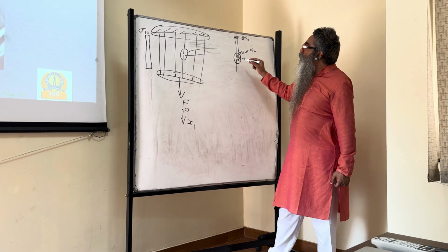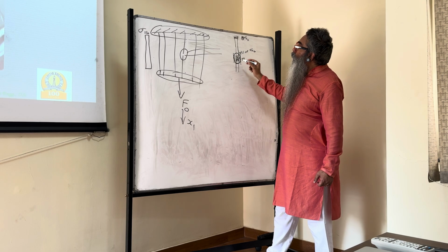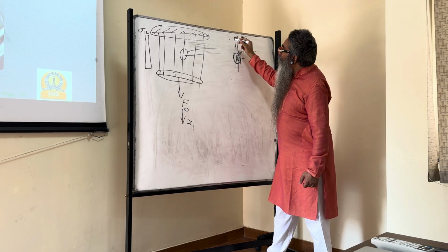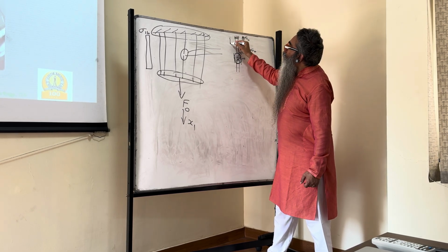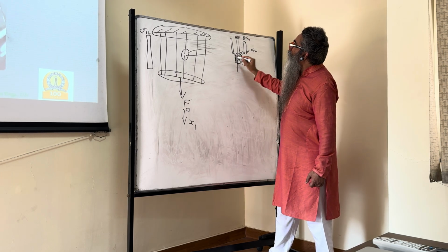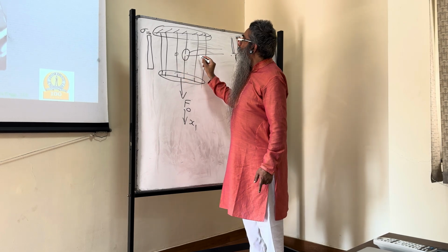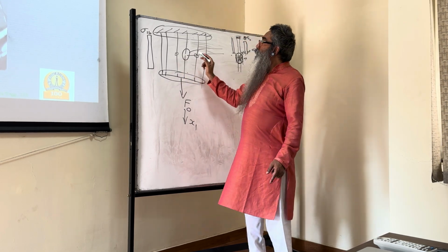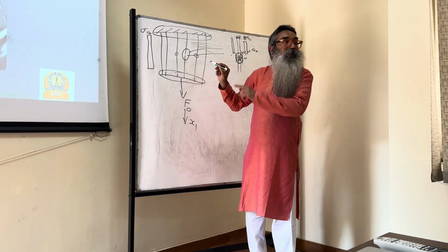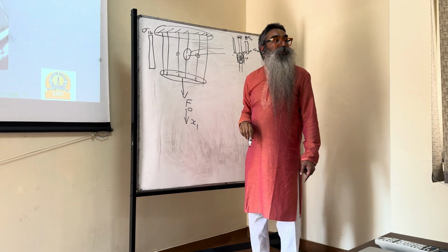Why that happens is because of the matrix that is surrounding this. So that matrix, immediately as soon as it sees a cut, it transfers that extra load to the next fiber, the adjacent fibers that are there, that get shared. So this fiber and this fiber start sharing this load, and therefore very quickly they let the fiber pick up.